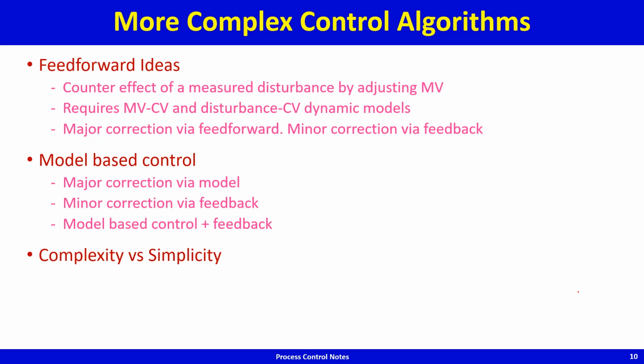Now you can see on-off control was very simple. The heater is on if the temperature is below set point. If the temperature increases above set point, switch off the heater. Just on-off. Very simple, primitive. But then this primitive control algorithm causes a sustained cycling, called a limit cycle.